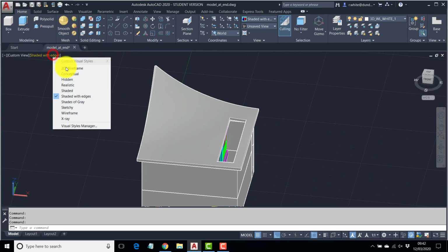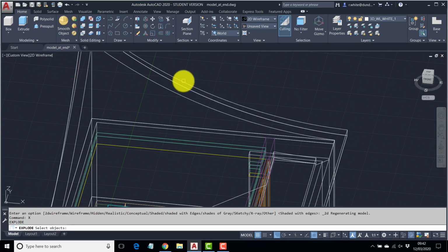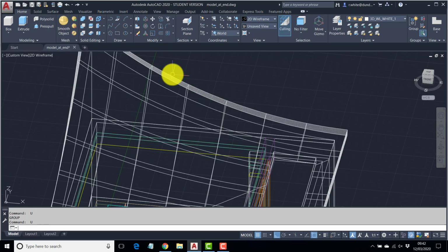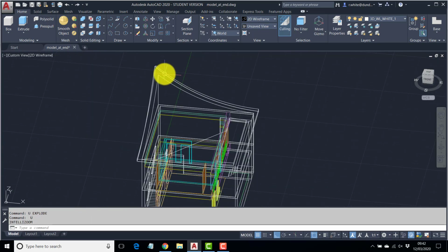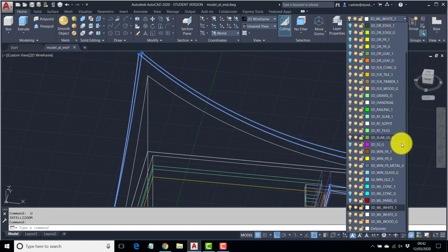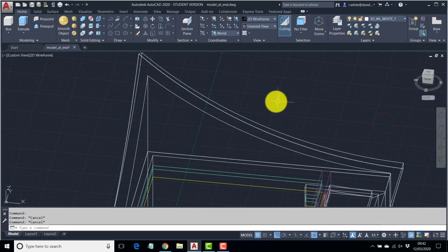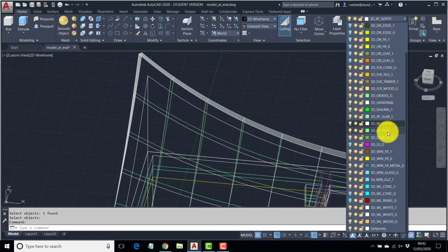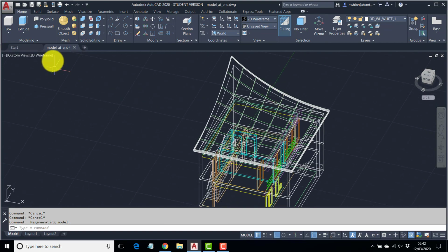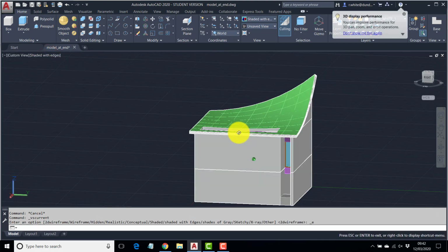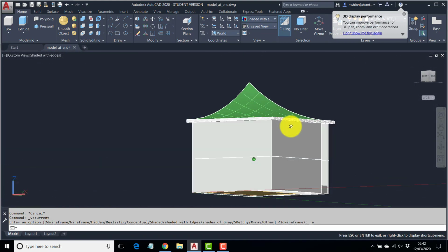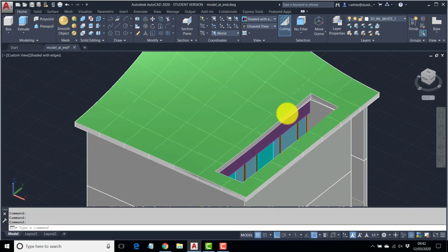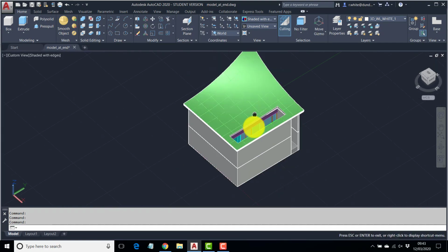It is a shame to explode this, but we can't change the layers materials just now if we don't. Put that onto the soffit layer first, because most of it's going to be soffit. So 3D roof soffit, then explode it, and we'll put just the top layer onto the roof tile. Let's see how crazy that looks. It's got its charm. Probably find that this is just where the water will run in, so it's going to keep the bamboo alive in that hole anyway.